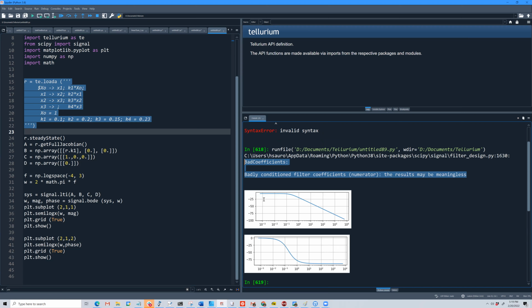And here you see the result. So this is the amplitude one, and that's the phase shift. And you see the phase starts at 0, okay, at low frequency, and then dives down to minus 90. That's basically minus 90 degrees, all right? The bandwidth is somewhere around here, okay, between these 2 markers. And this basically is the same as a first order system.